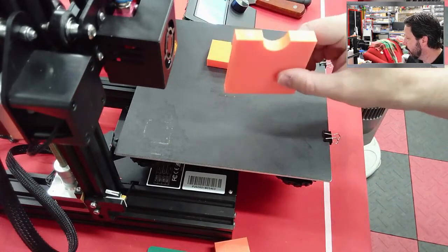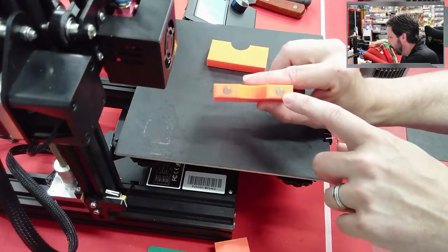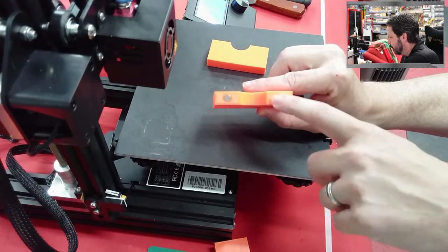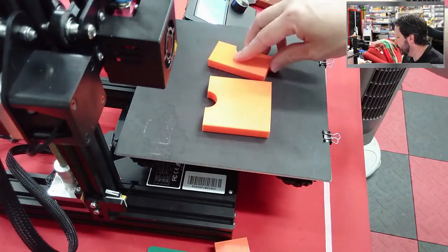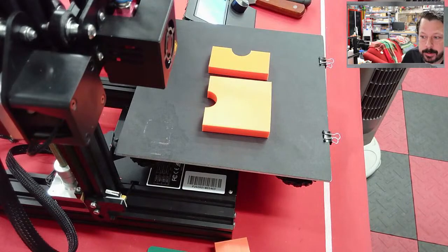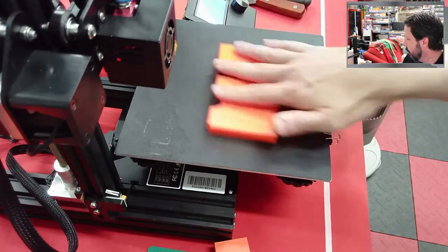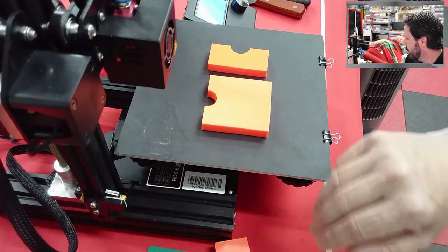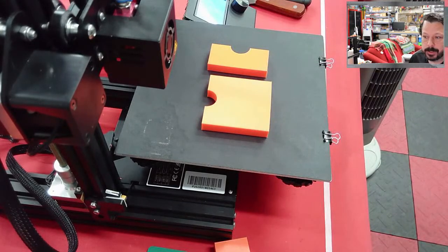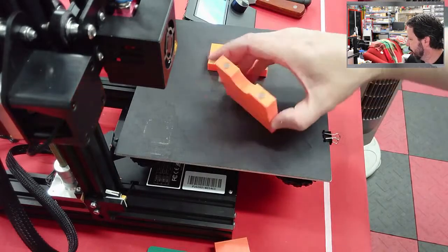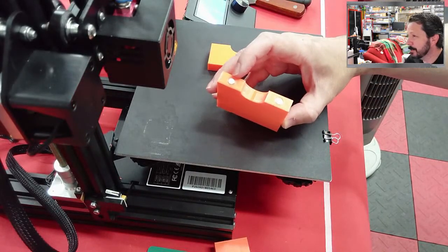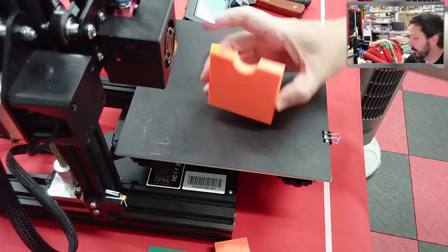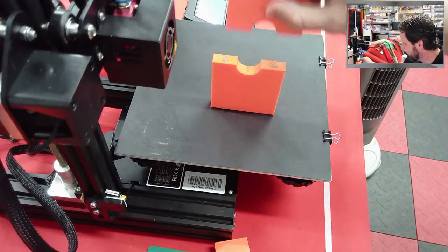So yes, if I didn't have the goal of keeping these perfect circles on the top, this would have been a much better way to print these parts. They wouldn't have had any problem as far as wanting to vibrate around or anything like that. So this would have been a better orientation, but for the one reason of wanting to keep these perfect circles on the top, that's why I printed it standing up.